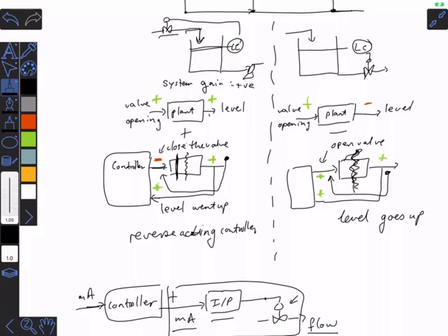In that case, I can say, well, the controller is conceptually outputting a valve opening between 0 and 1, where 0 is a closed valve and 1 is an open valve. I've hidden from you the sense of the valve. But I've said, look, we'll just make it happen on the system. We'll scale everything so that whatever the controller outputs, 0 is a closed valve and 100 is an open valve. Right, so I've hidden that from you.